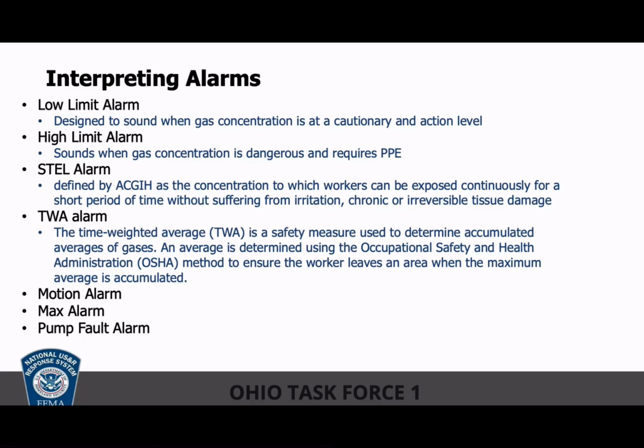And basically, we know that in the industry, people work with toxic gases all the time, and they do so without personal protective equipment, without respiratory protection. So the ACGIH has established STELs, which is basically how long you can work next to a specific toxic chemical: no longer than 15 minutes with 60-minute rest cycles, no more than 4 times in a day.